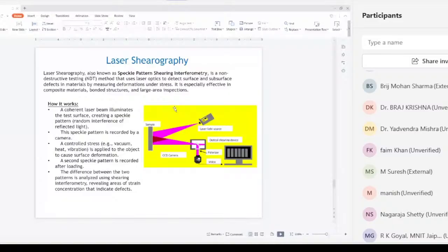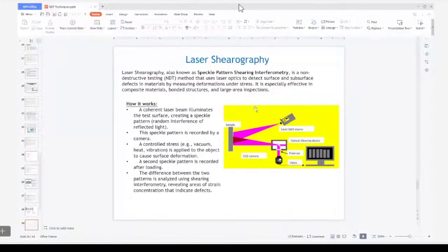And if I want to check the internal region, I can use a rotating probe technique. So there are many available. Mainly you see its usage in the oil and gas industry. In the additive field or aerospace, you don't come across eddy current technique usage. But this technique is well established. Certifications are available, and other industries exploit this technique for inspection of parts, mainly for surface defects.